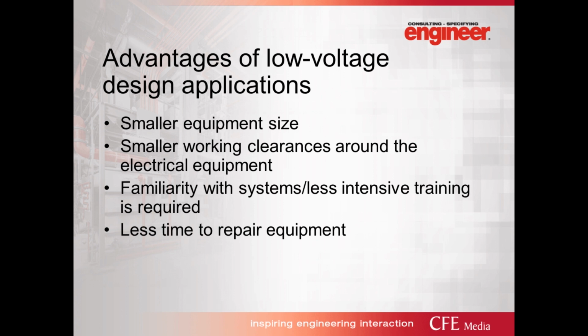This will affect your electrical room size. Also, many facility personnel are more familiar with the low voltage systems and require less intensive training for it than for the medium voltage system. The low voltage systems require less time to repair in case of failure.